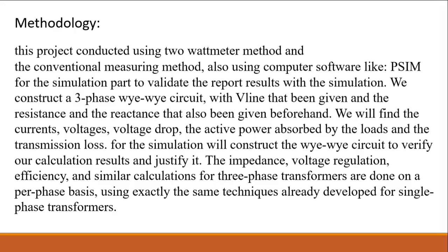We will find the currents, voltage drop, the active power absorbed by the loads, and the transmission loss for the simulation. We will construct the Y to Y circuit to verify our calculation result and justify it. So the impedance, voltage regulation, efficiency, and similar calculations for three-phase transformers are done on a per phase basis using exactly the same technique already developed for single phase transformers.